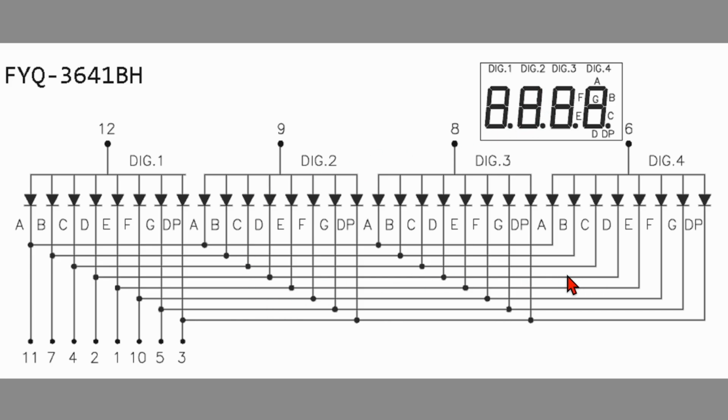And then we would keep cycling through. After we display digit 2, we'll lower pin 9 so that there will be no current flowing through these diodes here. And then we'll raise pin 8 and raise and lower some of the pins down here. We would lower the pins that we want to display.